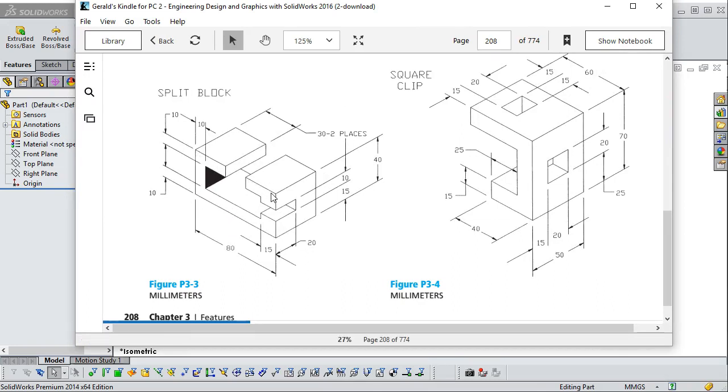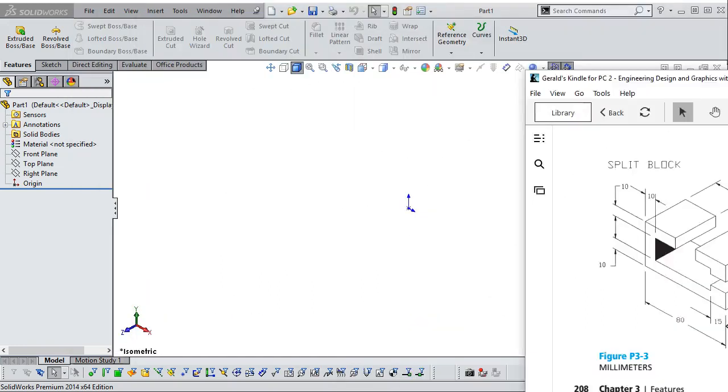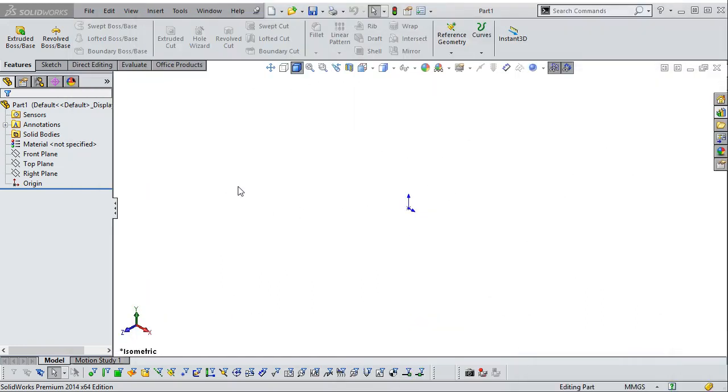Okay, so let's fly in the sketch, and the outside shape, and I'm going to go with whatever your gut kind of tells you. You see the shape, then that's what we're going to cut. This also has symmetry about the mid plane, so maybe we can take advantage of that as well. Since this is kind of optional, and we have 10 millimeters on the width, 10 millimeters, 10 millimeters, it's consistent all the way around. This might be a good one for a thin feature.